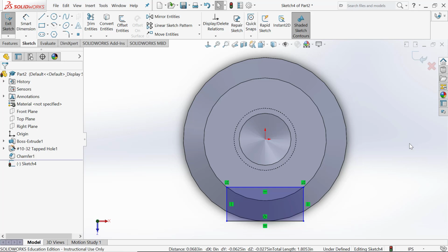Okay, first off, I don't know what's going on over here. Let's do that. All right, so left click on that line, hold down the shift button, click on the perimeter of the circle, add tangent. Okay, adding relations, guys, quiet please. Adding relations is something you absolutely have to learn. I just did it for 3 people. There's no reason that you should have trouble adding relations.